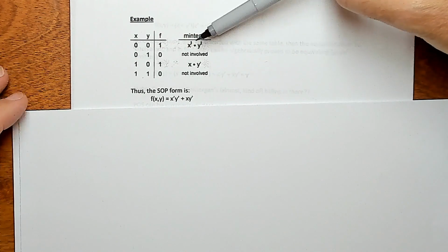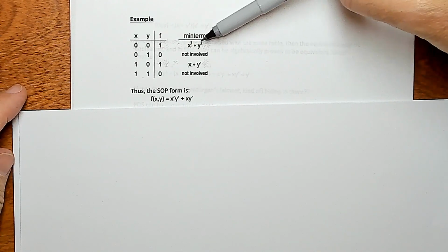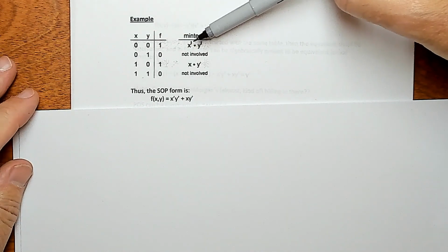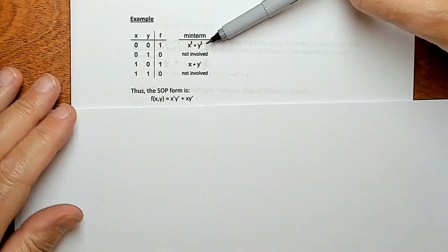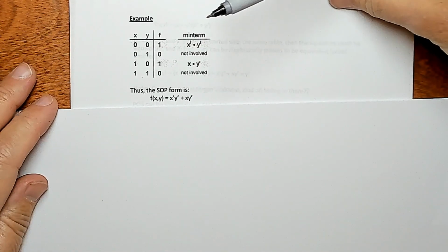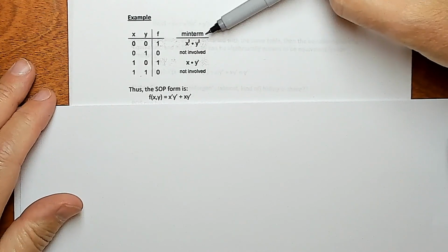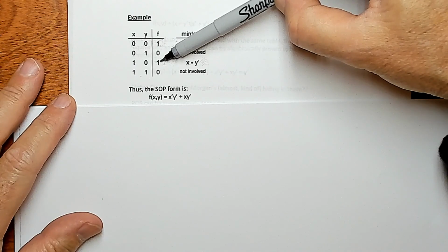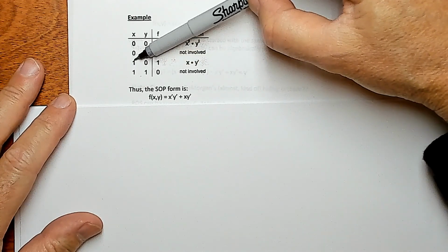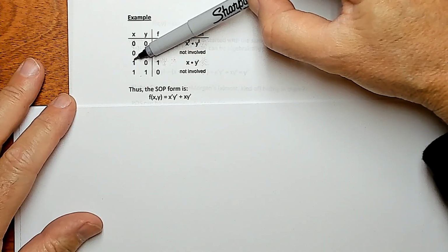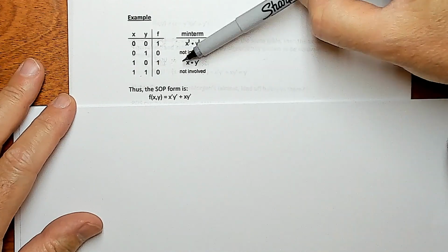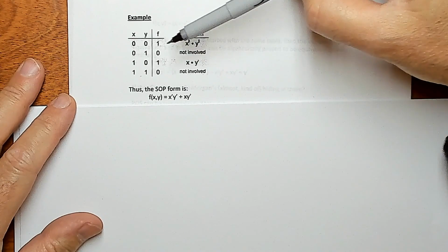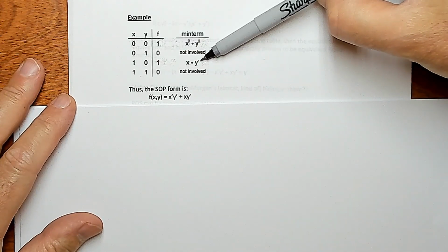I'm skipping the math reasons, the proof of why this works, but I hope you'll see it in the example. You'll see that it does work, but it makes intuitive sense when you see the whole thing. Okay, then this guy here, we have a 1 here, so we also need a min term, and then we look at the x's, and there's a 1 and a 0, so the 1 means do not have a not, and a 0 means we need a not.